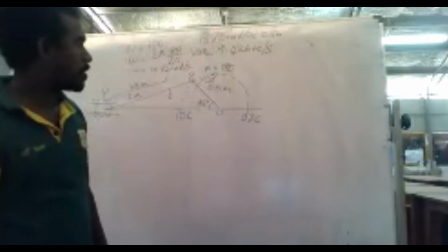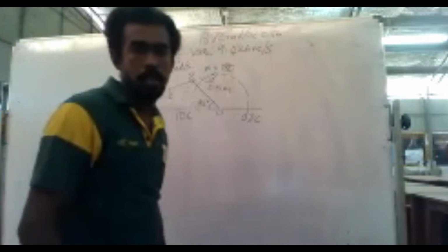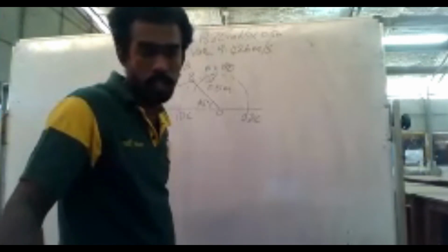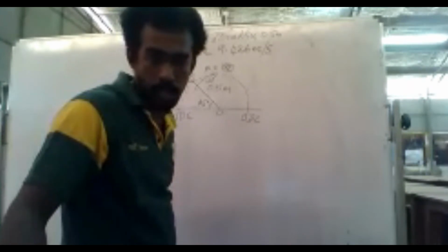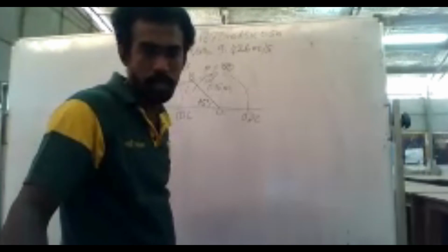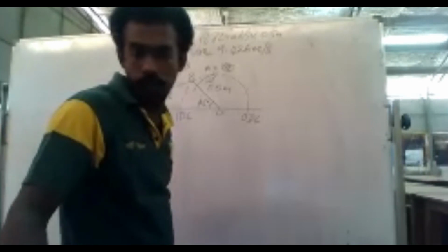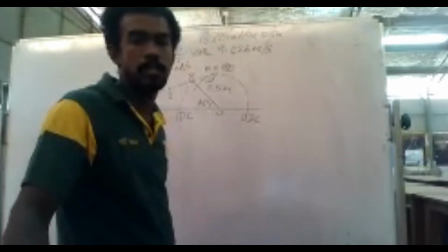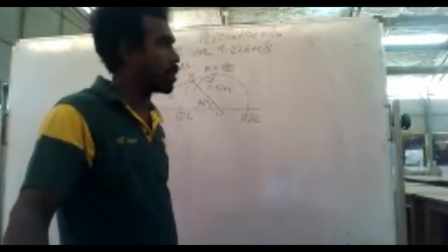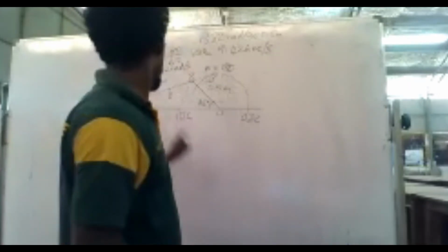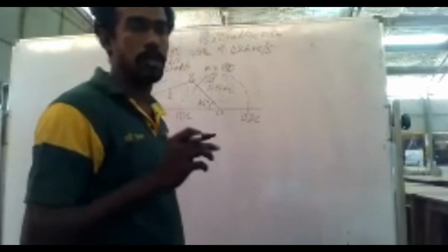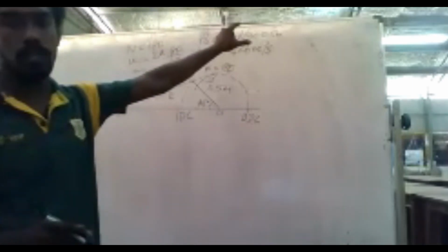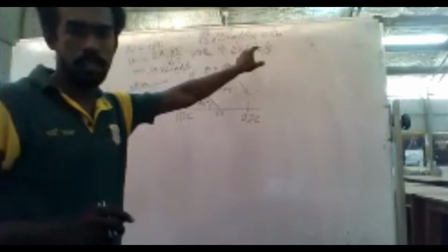Now I can start the velocity diagram, right? Angular velocity of the connecting rod, that's the question, right? Okay, we'll go one by one. From the velocity diagram, we need to find the angular velocity by measurement, right? So now we need a suitable scale, right? So 0.5 meter, here 2 meter is there. I will go for a particular scale factor, right? Only thing is you need to mention what your scale factor is.